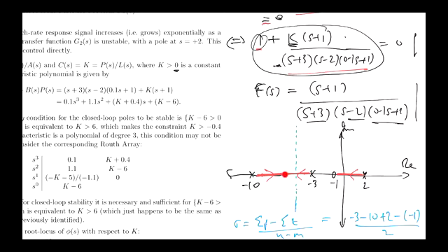Eventually they meet, and when they meet, they split apart in order to keep satisfying the phase condition, and one goes up and towards the asymptote, and one goes down towards the asymptote. Okay? Note, this is not about where they meet. This is about the anchor point for the asymptotes. The asymptotes tell you how the root locus behaves for very, very large values of k. The value of k when you're here may not be very, very large yet. This has nothing to do with where they meet. Okay?